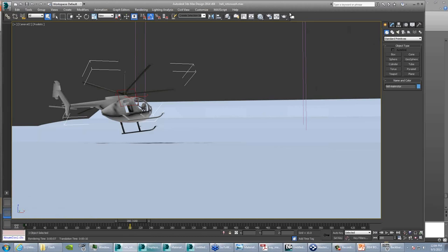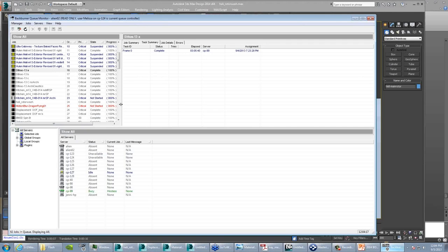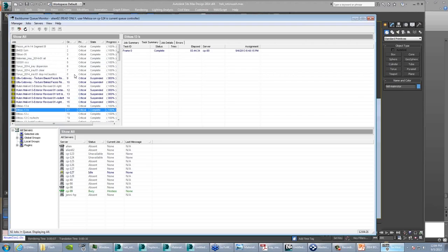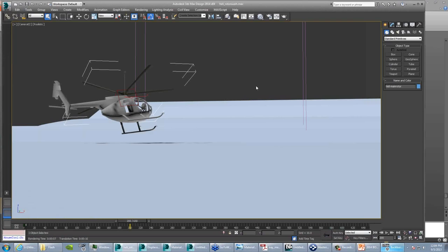Okay, can I net render and farm from 3D Max and Iray? Can you net render using Iray? Certainly. As far as Backburner is concerned, it's just like any other render. So we just run the server on the machines, and away it goes. Machines pick it up and do that. There is no distributed rendering, though, at least at this point. So you cannot utilize GPUs that are on another machine. You do have some options there, certainly with an animation that's easy enough for other machines to pick it up.